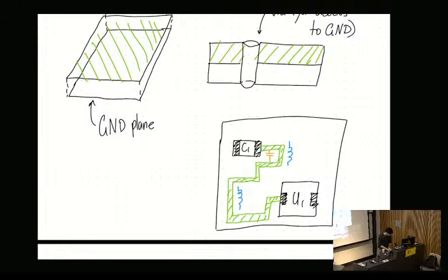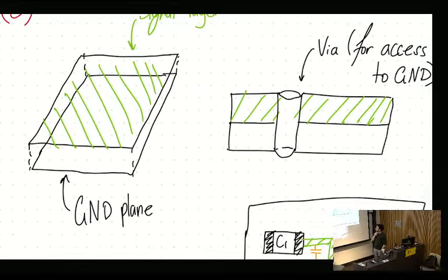Cool. The other probably more critical form of parasitic capacitance is between the two layers. Again, you have two metal layers. Naturally, a capacitance is going to form between them. So you're going to form a capacitance from this top layer here all the way down to this bottom layer here. So C parasitic. And if I was to draw that here, it'd be like that. That is the C parasitic.